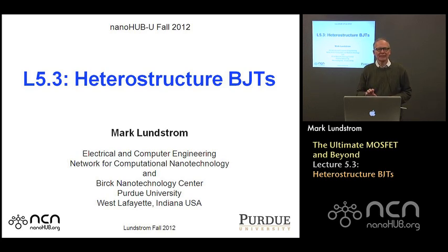Sometimes people think of this as a fundamentally different kind of transistor. You'll hear people say there are two kinds of transistors. There are field effect transistors that are voltage controlled devices. You control it with a gate voltage. And there are bipolar transistors that are current controlled devices. You control it with a base current. Actually, they operate by exactly the same barrier controlling principles.